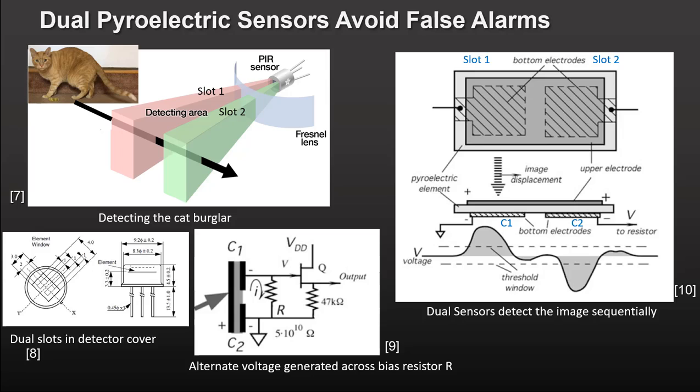A differential PIR detector is fabricated by applying two pairs of electrodes on both sides of a single plate. Each pair forms a capacitor that may be charged either by heat or by a mechanical stress. The electrodes on the upper side of the sensor are connected together, forming one continuous electrode. The two bottom electrodes are separated, creating two opposite serially connected capacitors. Depending on the side where the electrodes are positioned, the output signal will have either a positive or negative polarity for a thermally induced response.